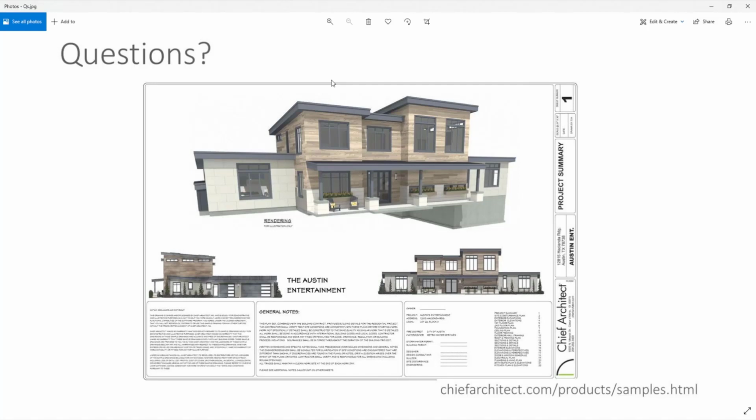So what I wanted to do was have that roof return, so it still looks like a gable coming around, with the hip coming across the front of that garage. And I know that I can do the auto roof return to make that happen. But the auto return takes the same pitch that the roof is.